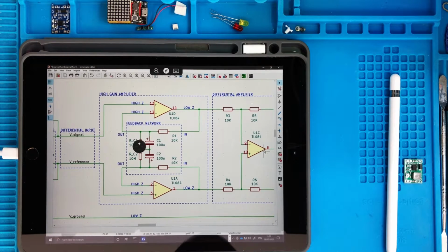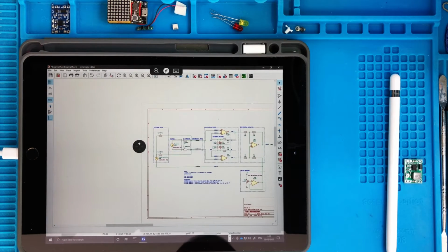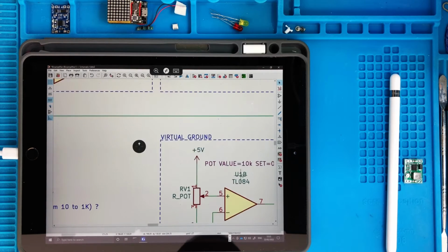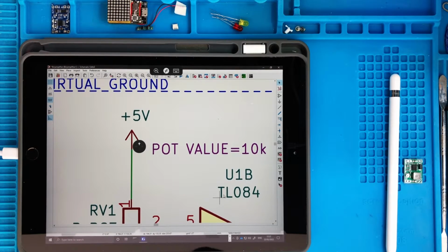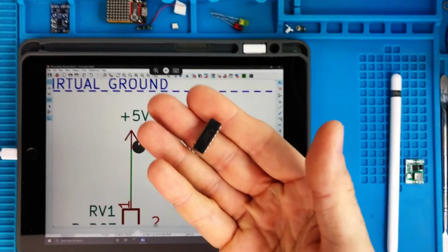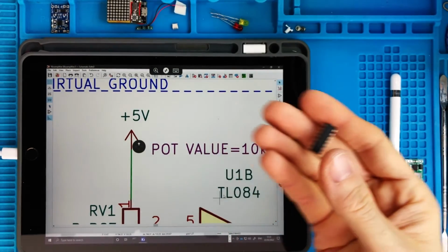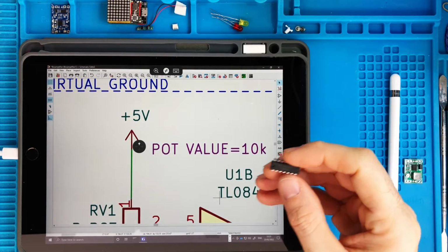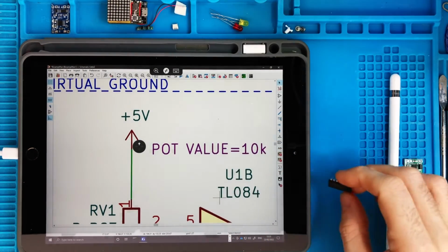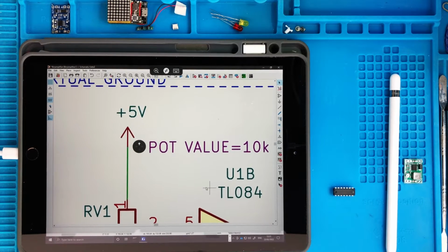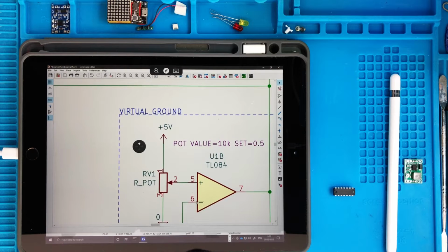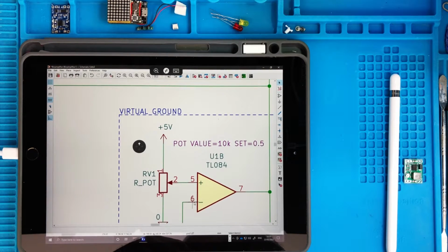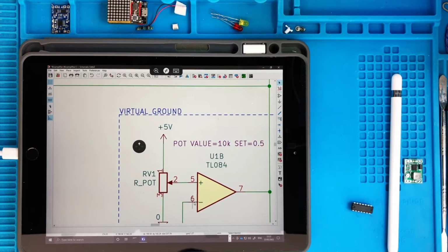U1A, U1C, and U1B as well, because this operational amplifier is a quadruple operational amplifier, so this microchip has 4 of them inside, A, B, C, and D. And so the nomenclature in this case is that this is U1, A, B, C, and D. Then the label that tells you what it is, a symbol that represents it, and the pin numbering that tells you what is connected to what, and eventually, if you need it, a SPICE model that will allow you to simulate it.